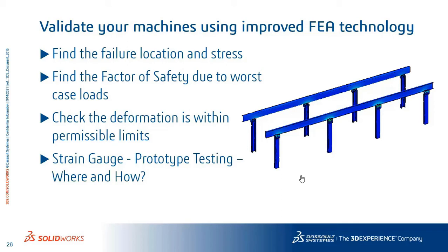So you can find out the failure location and stresses. You can find out the FOS due to the loading conditions. You can check whether the deformation is within the permissible limit or not, correct? Instead of doing the practical testing with the help of strain gauge, it can be done virtually inside SolidWorks itself.